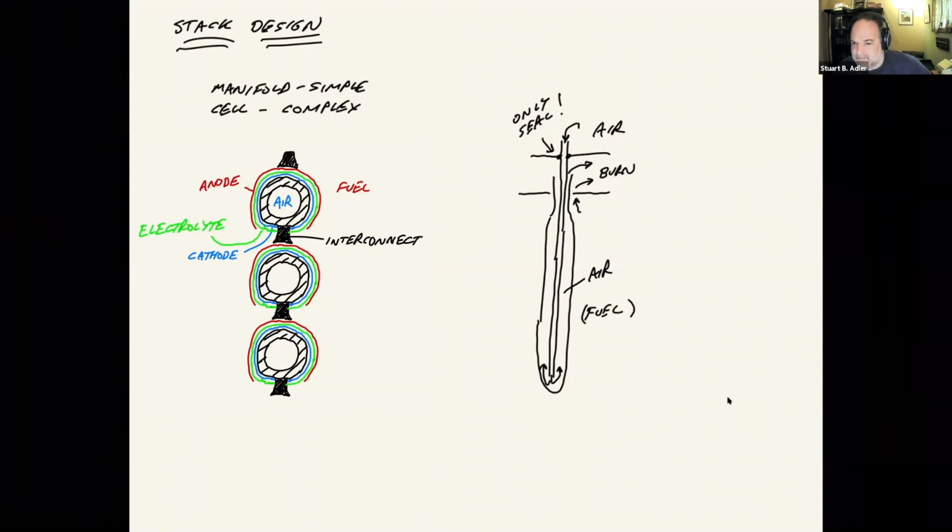which is fantastic because these things are hot, right? It's high temperature. The tubes can expand and contract. There's all kinds of thermal stresses you could imagine having, which you don't worry about because the thing can just grow and shrink with temperature. It's beautiful, right? The cells just sit on top of each other pretty much under gravity. They're connected to each other with these interconnects. It's a little bit more complicated than I'm making it out to be, but from a stack design standpoint, it's almost trivial. Why don't people do it anymore?